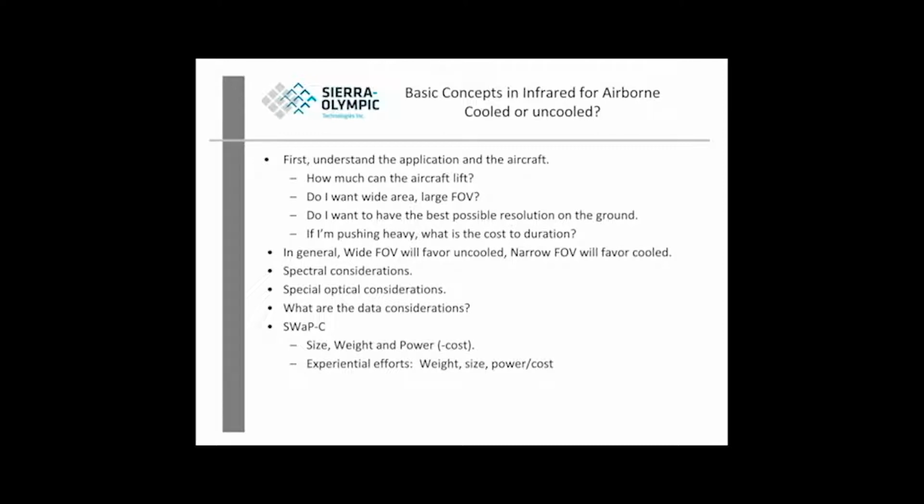So do I want a wide area? Am I surveying the county, or am I looking down at a person? Those are fundamental issues related to field of view, usually scaled to horizontal field of view. And then the other half of it is resolution. Resolution, you'll see in an upcoming graph, is what ground sample distance one pixel can generate. And that's a geometric calculation between focal length and pixel size.